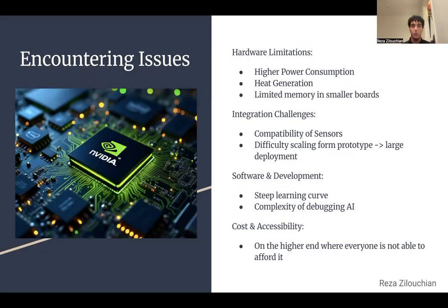For example, when they used an RDL interposer with local silicon interconnect bridges to push transfer speeds up to 10 terabits per second, the problem was thermal expansion. The GPU chiplets, the interposer, and the motherboard didn't expand evenly with the heat, which caused warping and failures. NVIDIA actually had to redesign the top metal layers and bump structure on their GPUs to fix that.